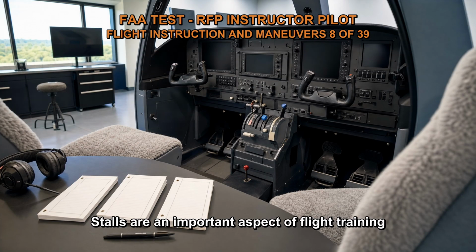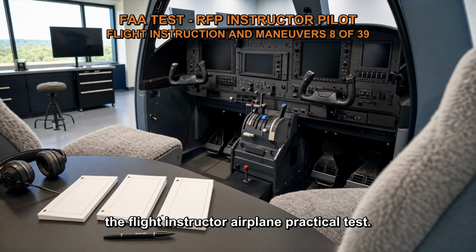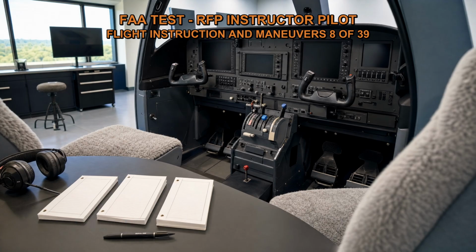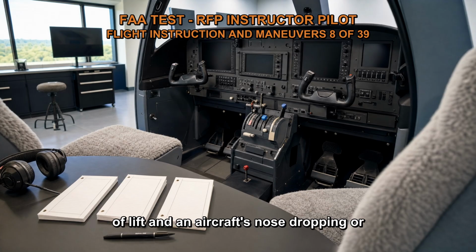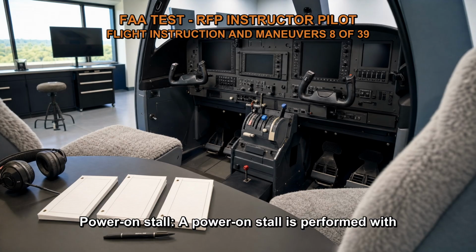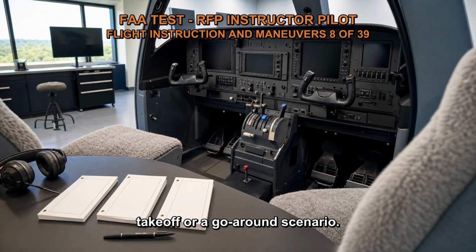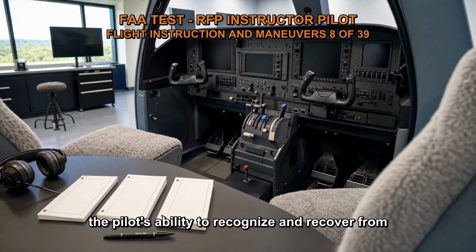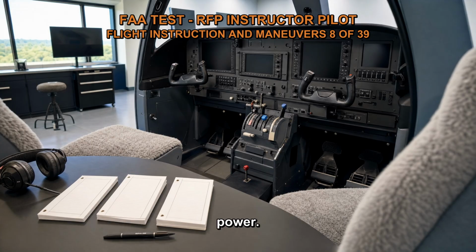Stalls are an important aspect of flight training and are typically evaluated during practical tests, including the flight instructor airplane practical test. Stalls are maneuvers where the critical angle of attack is exceeded, resulting in a temporary loss of lift and an aircraft's nose dropping or pitching uncontrollably. Power-on stall. A power-on stall is performed with the engine at a high power setting, simulating a takeoff or a go-around scenario. The purpose of this stall is to assess the pilot's ability to recognize and recover from a stall while experiencing the effects of high power.